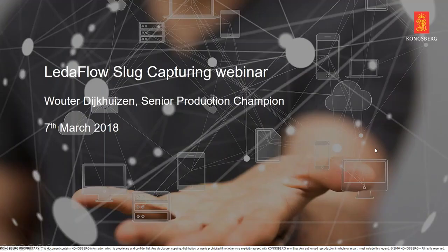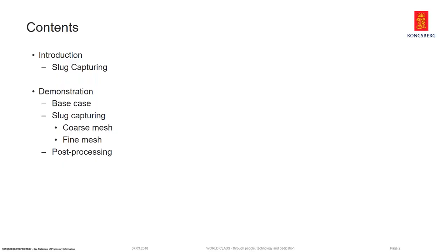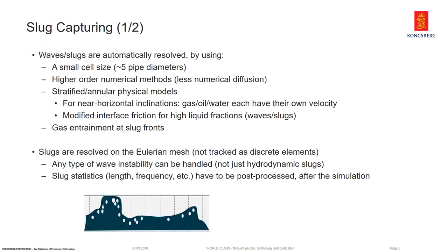Thank you, Mike, for the introduction. So this webinar is about slug capturing. I will quickly explain a little bit about the slug capturing technology and LedaFlow before we start, and then most of the time in this webinar will be spent on a live demonstration afterwards. So slug capturing is a technology where waves and slugs are automatically resolved by using a very small cell size, typically about 5 pipe diameters.